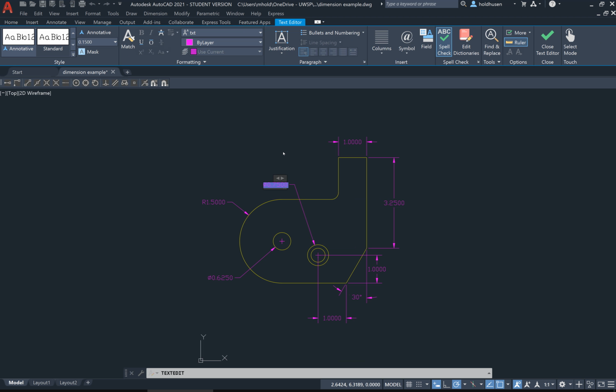Okay, so if I double click on it, right, and I move my cursor all the way to the other side, I can then come down like so. Actually, this guy, that's the counterbore. So I actually want to put above this the inner diameter, right? So that inner diameter is 0.5, and I just typed in 0.5, and you can make changes here, but you come up here to symbol, okay, and I can put in the diameter symbol in front of it, and it'll put that in there for you, okay?